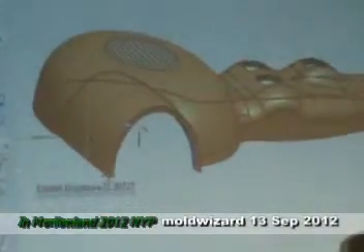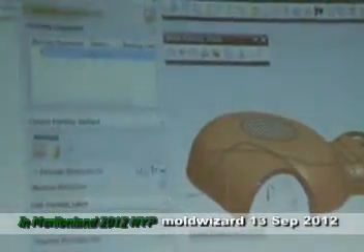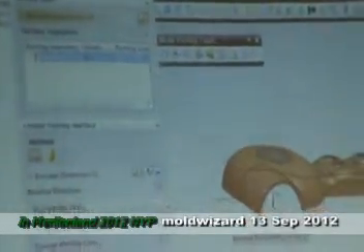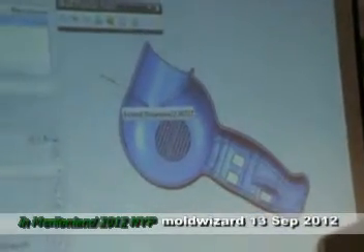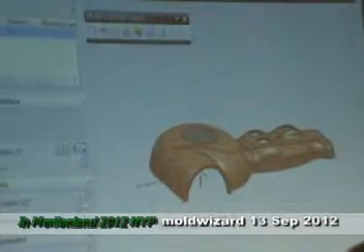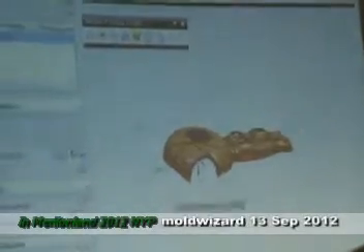So now we need to define it and let the software create this parting surface using different commands from the other part, because this part is a planar face and this part is not. So we need a different method. For this, we need to edit the parting line.